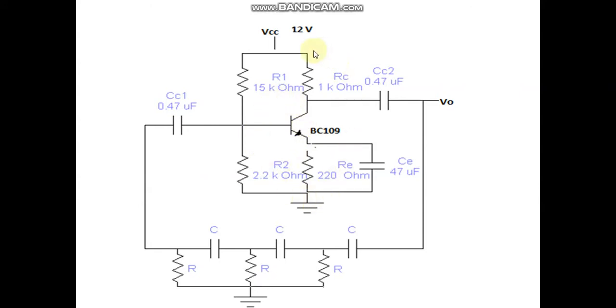The oscillator produces its own waveforms, and here it produces a sinusoidal waveform. The frequencies an RC phase shift oscillator produces are lower frequencies, ranging from 1 kilohertz up to 5 or 10 kilohertz. We recommend the RC phase shift oscillator for lower frequency ranges, usually audio frequencies, like 1 kilohertz, 2 kilohertz, 3 kilohertz. If you want to generate these, you can prefer the RC phase shift network.